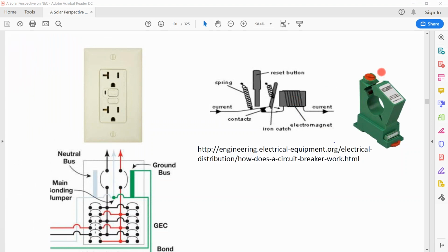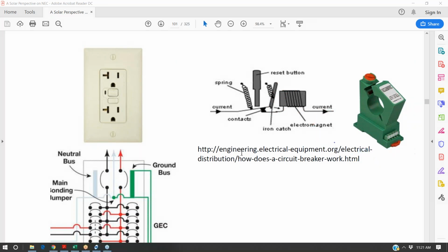Similar to how an electrician can clamp around a conductor with his clamp meter and through induction monitor the current flowing through it, a ground fault protection circuit has an additional monitor so that it can catch smaller ground fault currents, not large enough to cause the breaker to open up due to the metal warping.